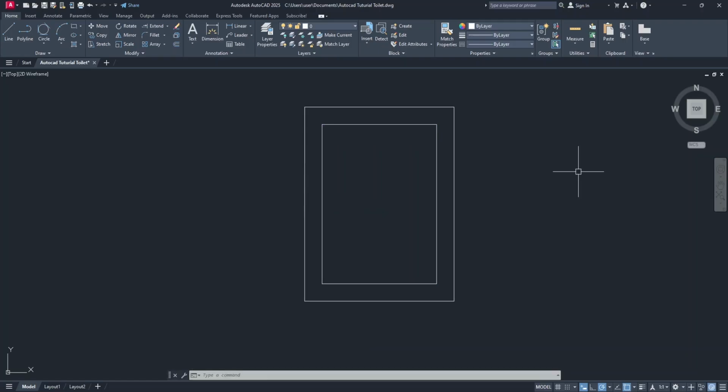And now to make our door, we have to cut an opening for the door. To do that, it's really simple. Simply select your line, come here and point to this direction and type 150. For the inches, just type 6 and then press enter. Point downward and just click at that intersection mark.